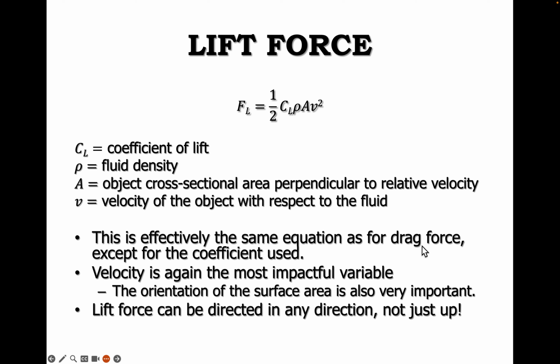Just like with drag force there, velocity is going to play the greatest impact on lift force. What's also important, though, is the orientation of that surface area. Okay, and we'll talk about that a little bit later on in some of the slides. Now, what's important to note is while lift force, the name of it, lift, we always think of coming up there. Okay, lift force can also act down as well. Lift force could also act left. Lift force could also act right. Okay, so lift force can happen in any direction, not just up.